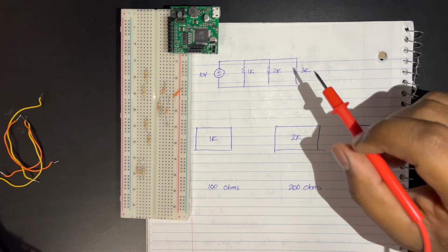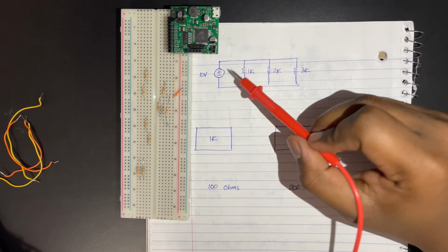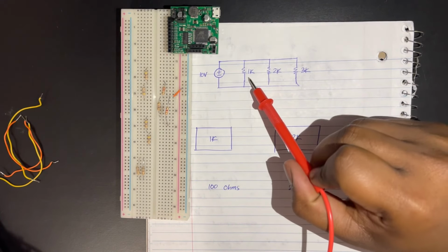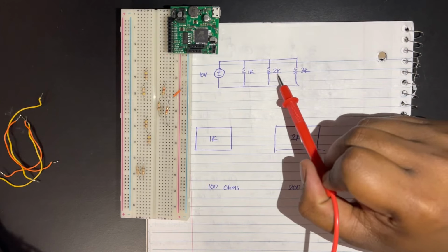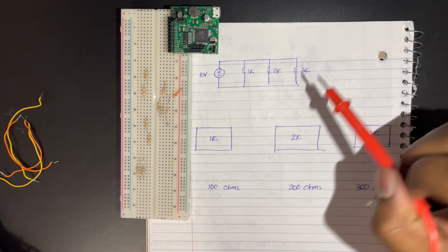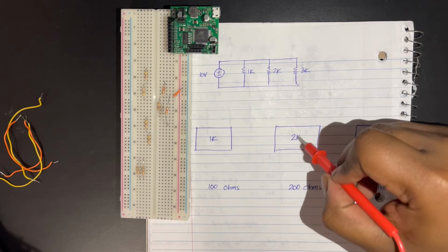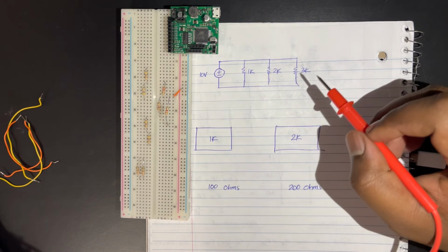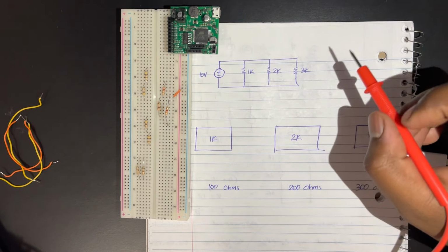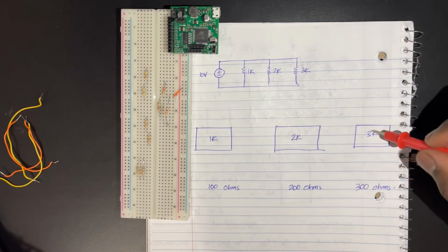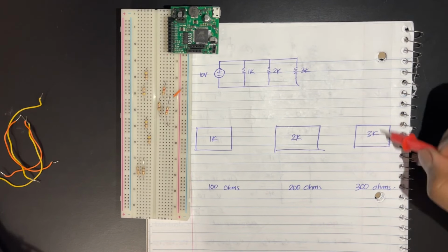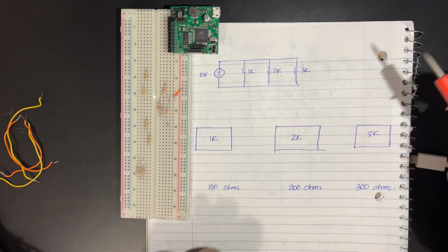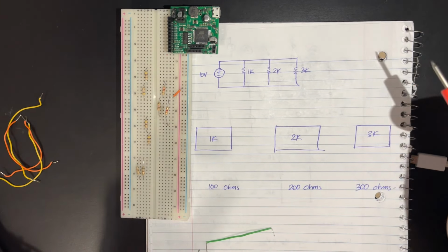All right, so the circuit setup. Like I said before, I'm going to be supplying 10 volts. Over here I'm going to have a 1 kilo ohm resistor, 2 kilo ohm and 3 kilo ohm in parallel, right? For the 2 kilo ohm, I didn't get exactly 2 kilo ohm, I got somewhere around 2.24 kilo ohm resistor, and it's a similar case over here, like 3.34 or something like that, but that's totally okay. I measured it, so I know what to expect.